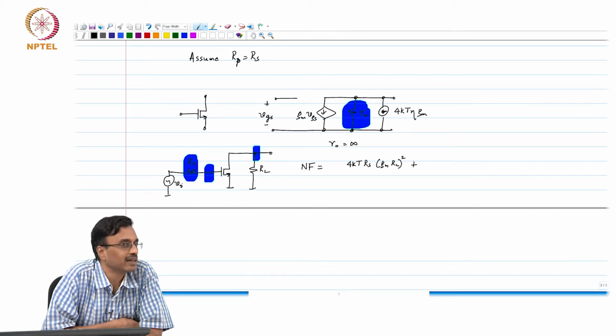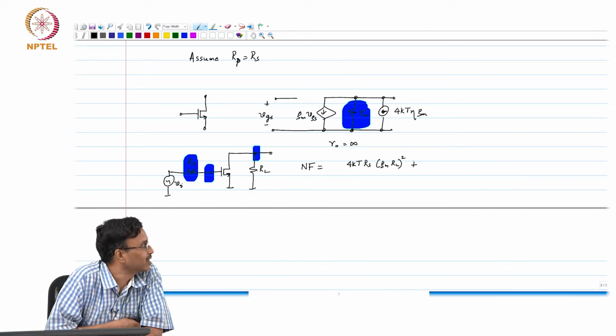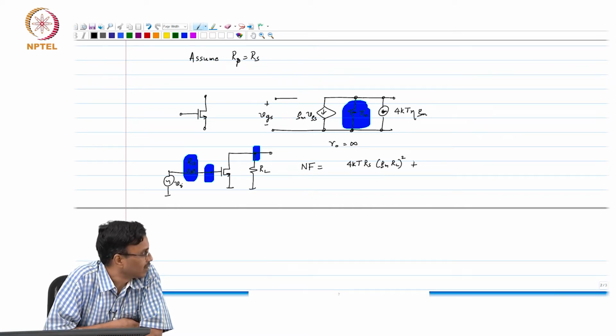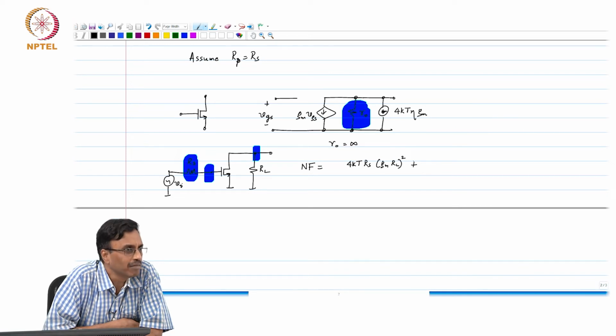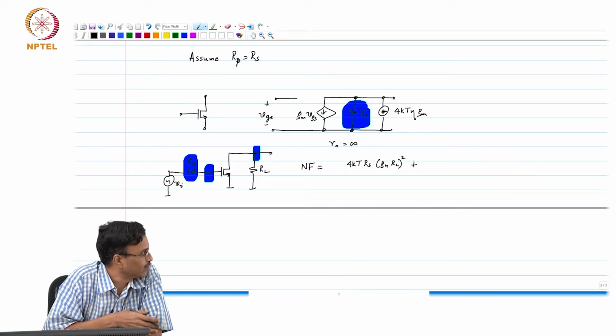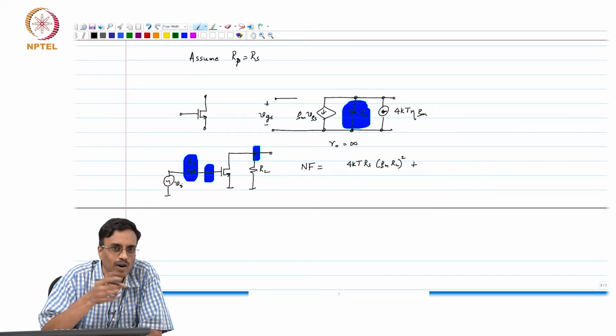The main thing here is the transistor. How many noise sources do we have? Three noise sources. Of course, with three noise sources we can all do this in our minds. But you can imagine what will happen if you have 50 transistors like this, and tons of noise sources, and one output, and I made our life simple by assuming ro is infinity and there are no parasitic capacitances, etc. In reality, all that stuff is going to come in, and it is going to be a mess.